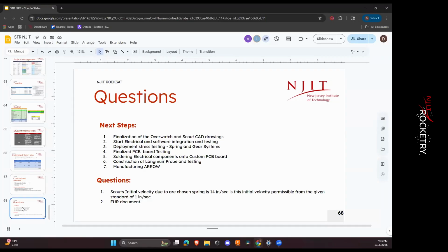Yeah, so it's kind of a two-way approach. One's protecting against the actual inrush, and the other approach is trying to limit the inrush. But with the fuse, yeah, the polyfuses aren't great for catching these. They typically don't. The polyfuses I was referring to are actually on the vehicle themselves. So they absolutely won't trip during this, so you're not going to make the rocket trip.